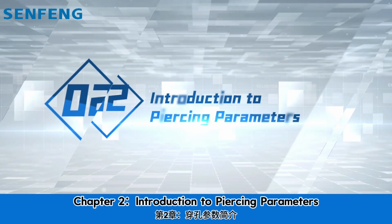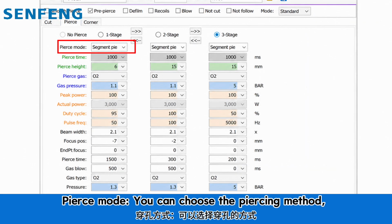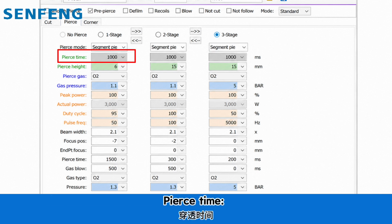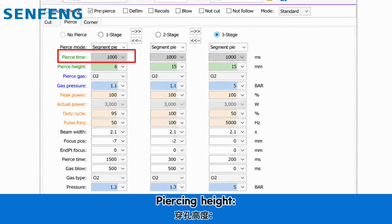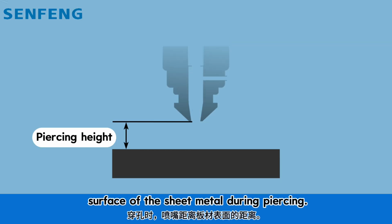Chapter 2. Introduction to Piercing Parameters. Pierce mode. You can choose the piercing method, such as segmented piercing, nozzle step, etc. Pierce time. The duration of laser piercing during the piercing process. Piercing height. The distance between the nozzle and the surface of the sheet metal during piercing.